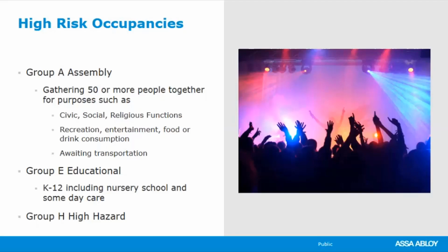And Group H, high hazard, is not a high occupancy. In fact, it's a non-occupied space. It's going to be some kind of a storage room, but the materials are either highly flammable or prone to explode, and therefore they're considered high hazard and high risk.